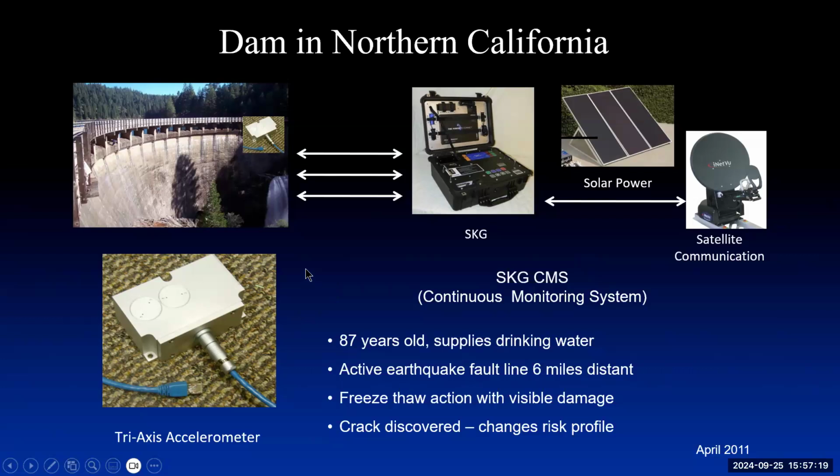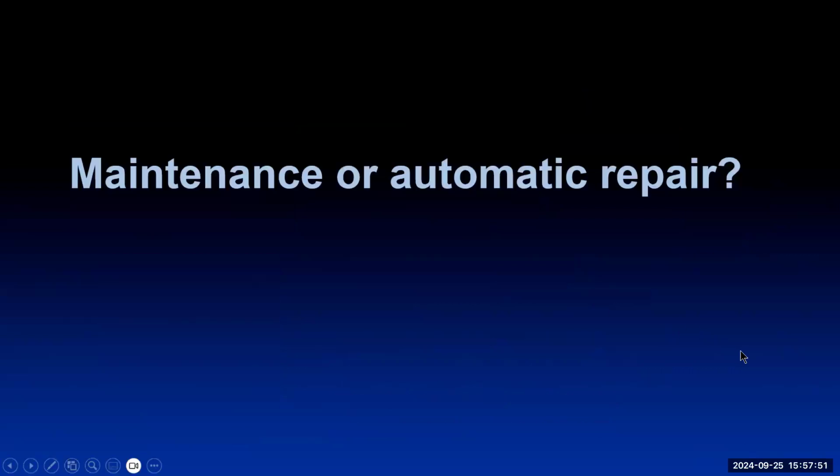We analyzed that dam, and by analyzing a lot of modes of vibration of the dam, we're able to say there is a crack in a certain position in the dam. So one of the project managers went to have a look and asked me where. So I told him where I thought it was, and he said, quite right. It's about 1 inch thick, and it's exactly where you said it would be.